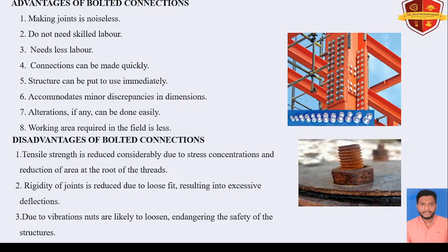Advantages of bolted connection compared to welded connection. First one is making the joint is noiseless. It does not need skilled labor. It needs less labor. Connections can be made quickly. The structure can be put to use immediately. Alterations, if any, can be done easily. Working area required in the field is less.